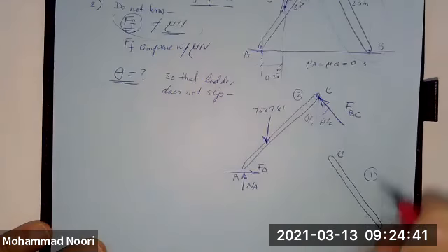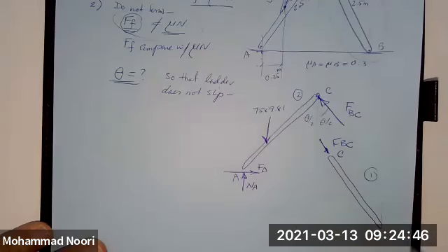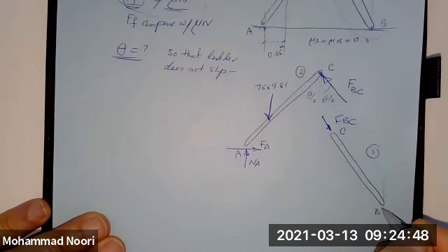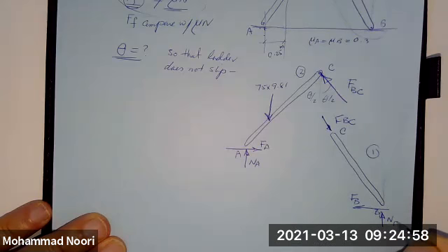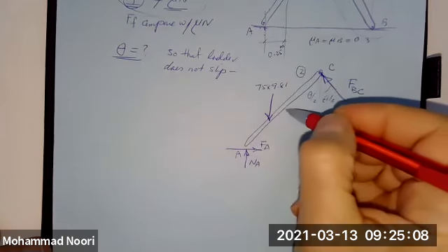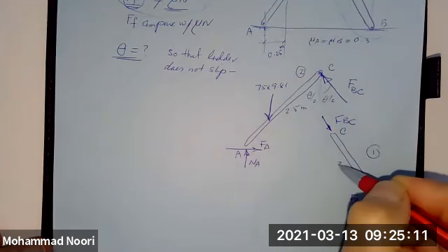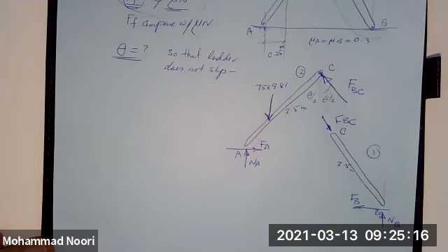So when it comes to this free body diagram, you have this force BC, and then at this end, again, you will have what? This leg may also slip that way, so the force of friction at B would also be this way, and this is the normal force at B. So these are the two free body diagrams that you need to draw. Any questions? The length of each piece is given as 2.5 meters, and that's it.